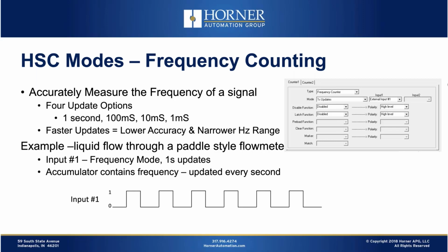If you have a relatively slow moving application, you don't want to be over calculating your frequency and having instability that you don't really need. Okay, so that's the setup there. Select frequency and you select your update rate.